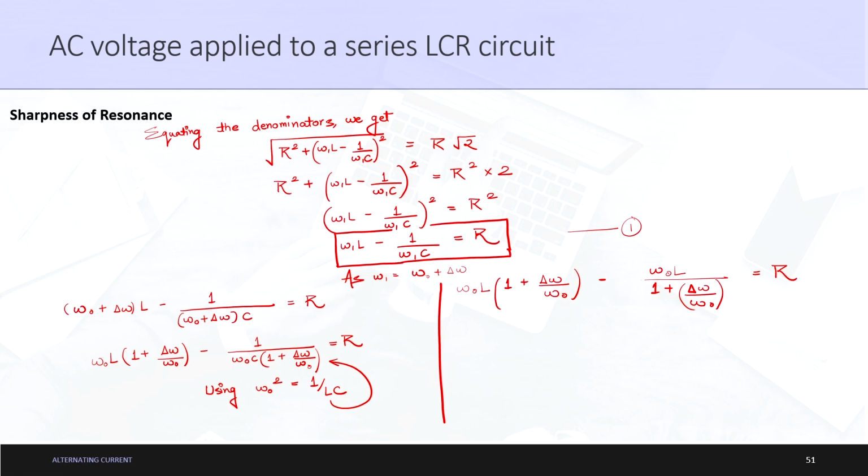Okay. So, to obtain this I just divided and multiplied by omega naught. This omega naught square is 1 upon L C, C got cancelled and therefore L was obtained in the numerator, and because omega naught was already there, we got omega naught L in the numerator, right. And this was already there, so nothing changed till this point. Okay.